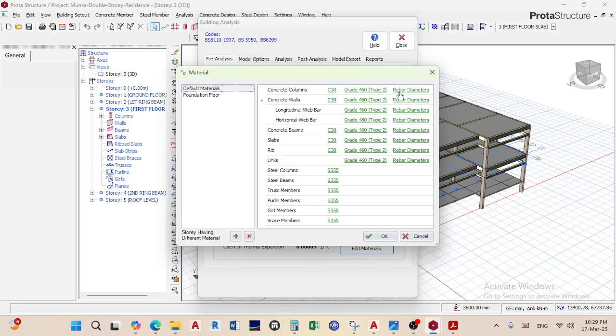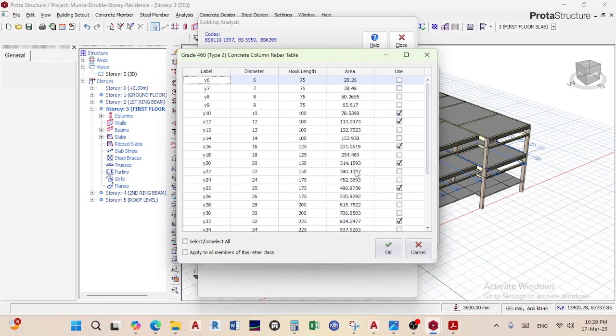Okay, rebar for my concrete columns, I want a minimum of... these are 200 by 400. Okay, I can use Y12, minimum Y12, maximum Y16. I do not need these other ones. Section is too small to have Y40 of it. So 12 or 16 for my columns.